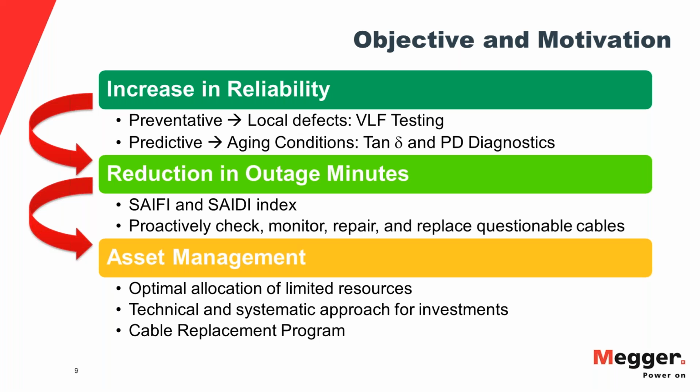So cable testing and diagnostics is not really there to have an immediate action. You know, you want to learn, or at least you want to prevent and avoid any critical emergency conditions that suddenly the circuit fails. But in the long run, the asset management is after allocation of resources, and every utility has budget constraints.